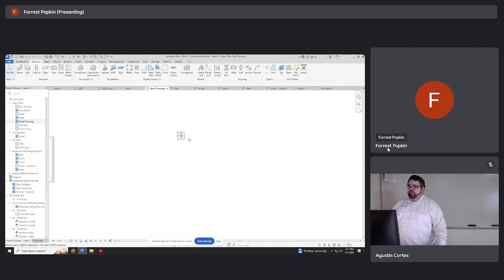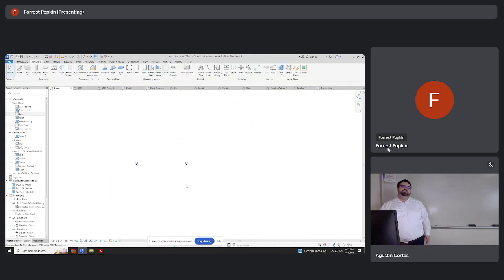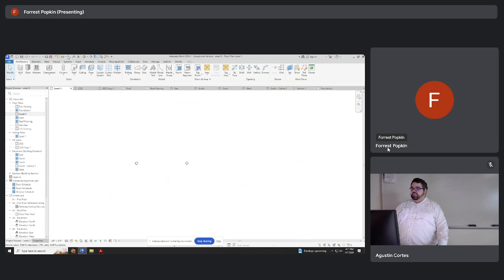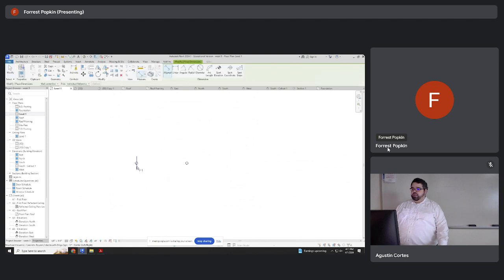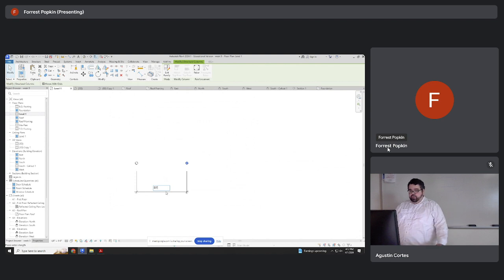So if I were to create a building with this type of framing in mind, you still have to consider what is our typical framing spacing. Now, the thing about concrete buildings is that they are a lot heavier, and you can get away with fewer in certain dimensions, but you still should probably be aiming for about 20 feet on center before you really break the bank. So in this instance, I can just apply 2. I can do something like this and type in the value. I get my center line.